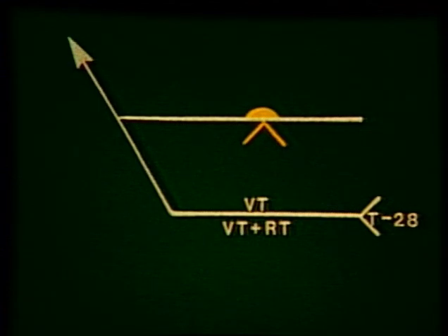This symbol shows a single V-groove weld with melt-through to be inspected on the arrow side, using a combination of visual and radiographic testing. The other side of the joint is to be visually inspected, and details of the inspection can be found in a procedure called T28.